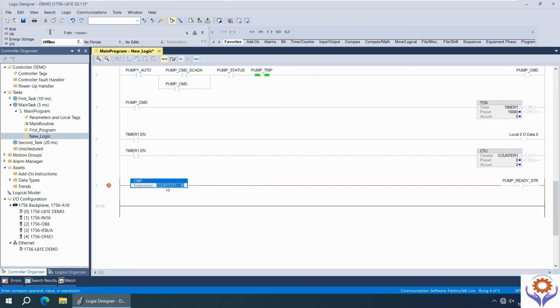And another thing, you don't know where the problem is, but you already know that if the red color is there, it means there is some issue in the rung. Maybe many rungs have the same issues, but you need to know what the problem is. So you have to validate your application. Once you validate, you can find the error.